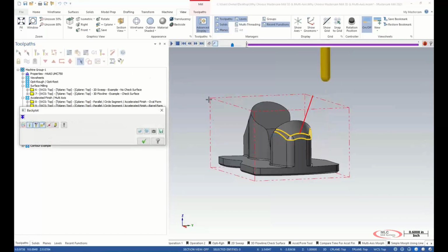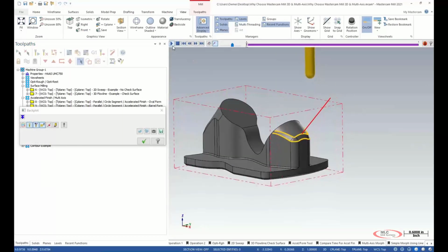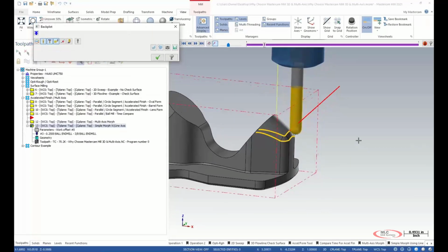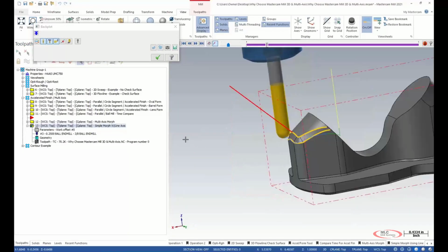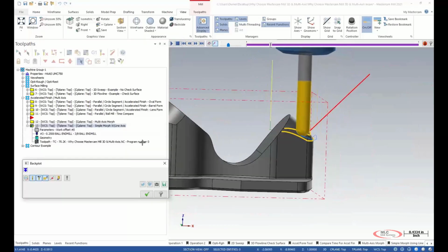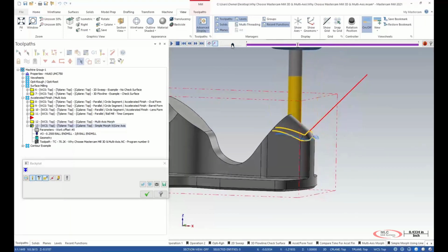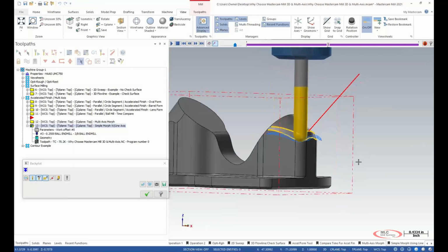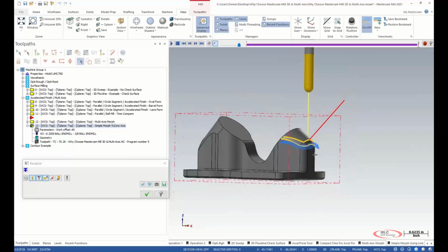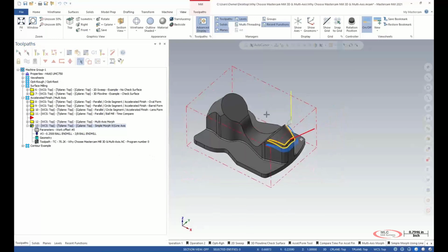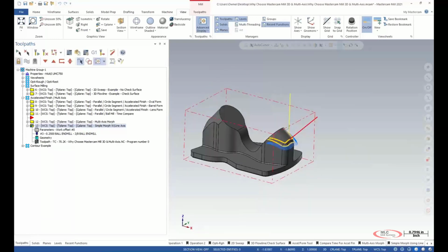We'll backplot this toolpath. And we'll continue on here. And on this one, being that the machine we're on, it's not going to follow that 45-degree there, so we'll have to tilt that at a 5-axis here in a minute. So there's our morph toolpath using a 4-axis machine. This machine is a Haas UMC 750, so it does matter how this part is set up on how it's going to tilt for your 4-axis.